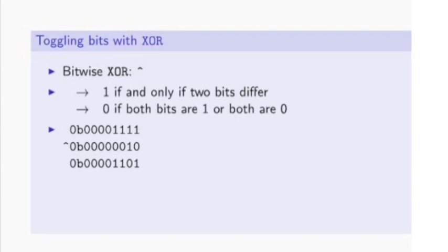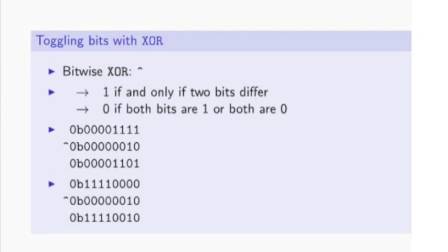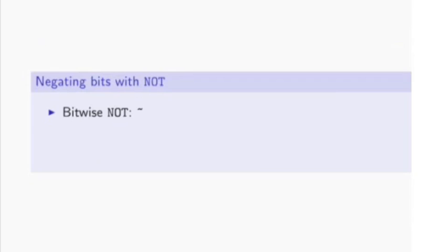And I want to turn one of them off. I want to turn off the PB1. I can XOR it with this number. All the ones that are on stay on because 1 XOR 0 is 1. All the ones that are off stay off. And then the one that I selected gets flipped. Awesome. You're going to have to work through the bitwise logic yourself for the others. I'll show you how this is all used in a summary in a few.